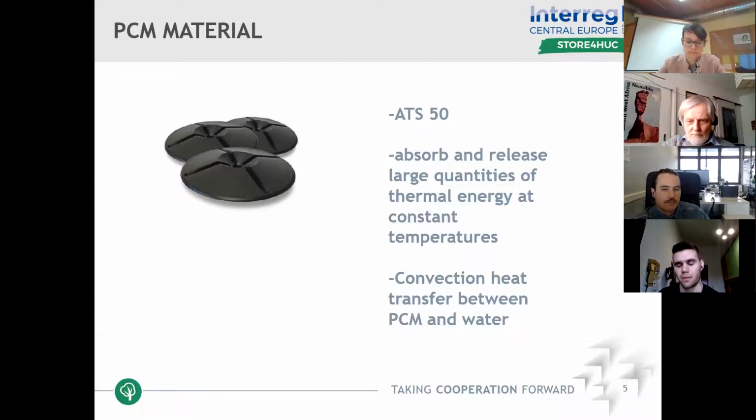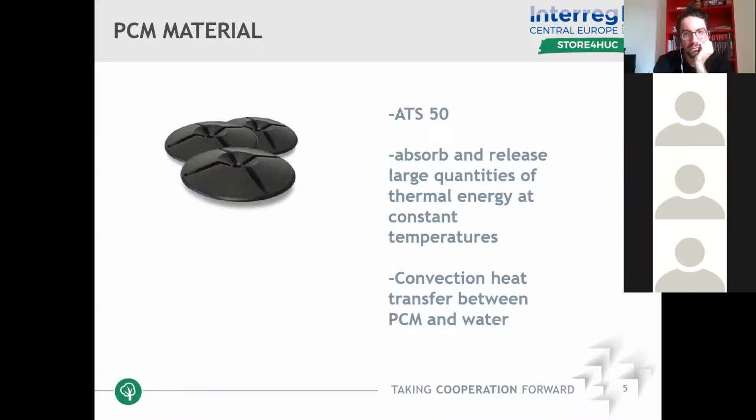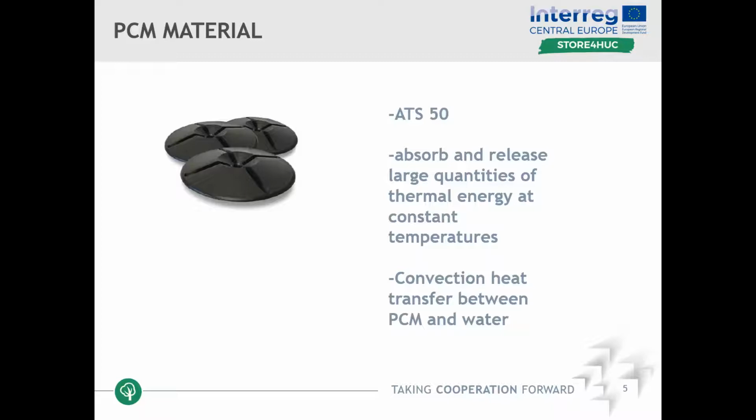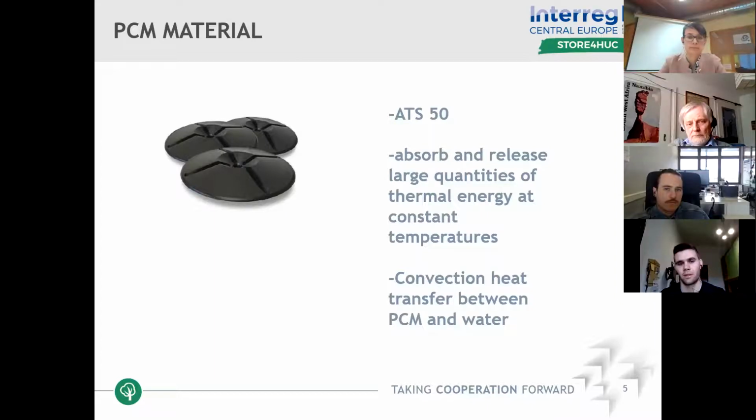The good thing here is that this material absorbs and releases large quantities of thermal energy at constant temperatures. So, for example, if this material cools down, it will release energy, and when its temperature reaches 50 degrees, it will still be releasing energy while staying at the constant temperature of 50 degrees. So that will keep the tank warm.